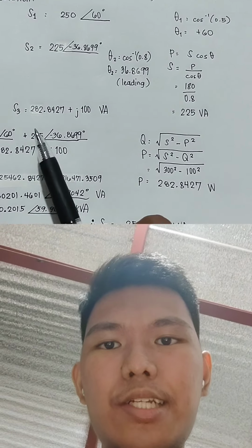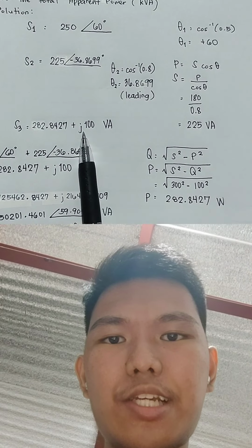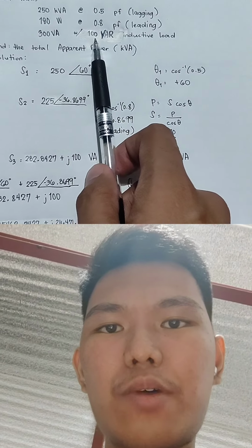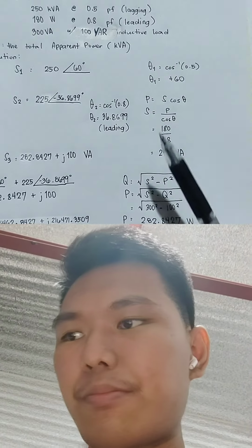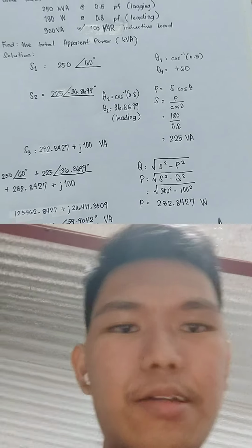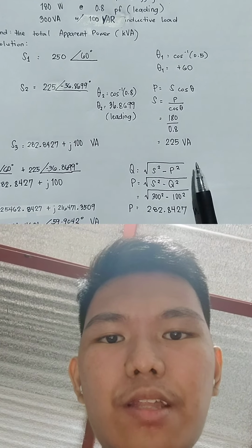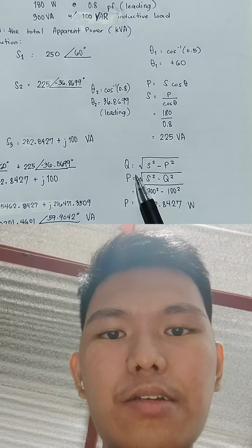Now, for our S3 equals 282.8427 plus j100 VA. As we can see, we have a given 300 VA with 100 var inductive load. Since it is inductive, we will use the Pythagorean theorem or the power triangle. Q equals square root of S squared minus P squared. Since we have the given Q, the 100 var, we will equate the formula.